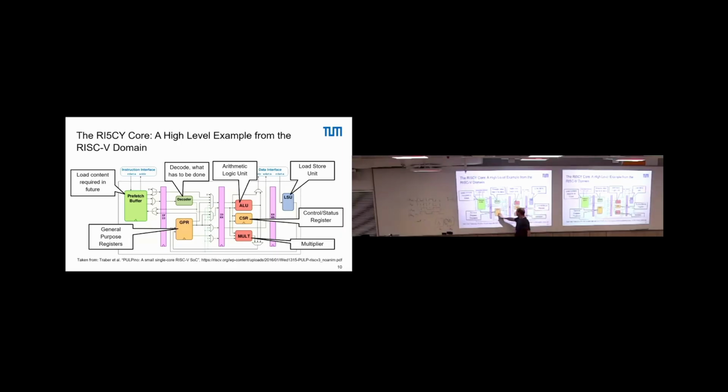Kind of, yes. This general purpose register is a register which is not dedicated to specific addresses or something like that. You can use it for any operation running on the core. For instance, you can feed back some intermediate multiplication results if you need to further process them, or output any result from the ALU there, so that you do not have to write them back into the data memory and reload for another round. Okay?